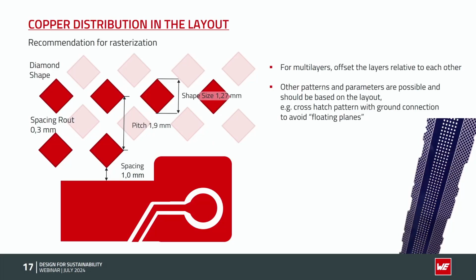This is an example. If you want to use copper dots, this can be a design rule for it. It has to fit to the layout. If you have a full plain area, there should be more dots. If you have a light, dense signal layout, it can be fewer dots, but a generous recommendation could be such a feature.